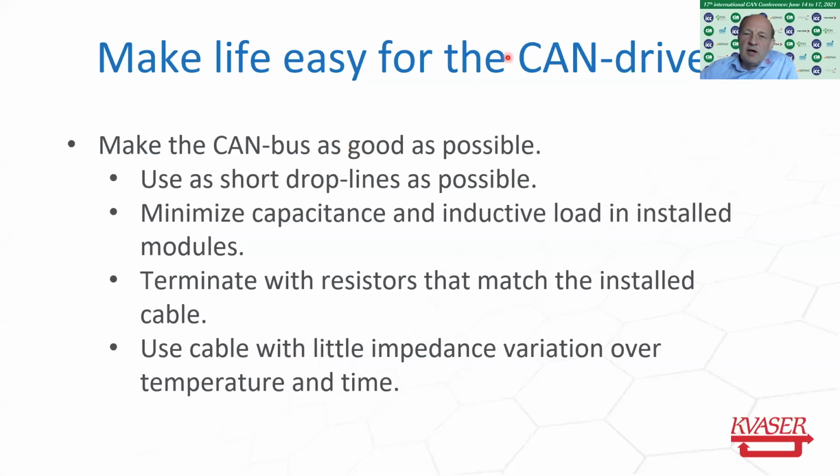So you can do a lot with the CAN drivers, but there's no reason not to optimize the CAN bus system as such before you try to buy expensive CAN drivers to solve the problems you have made yourself by making a bad CAN bus layout.